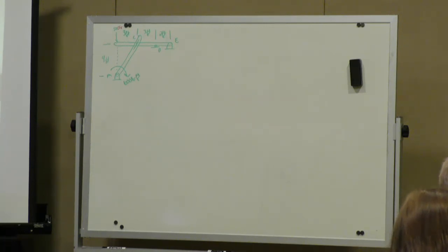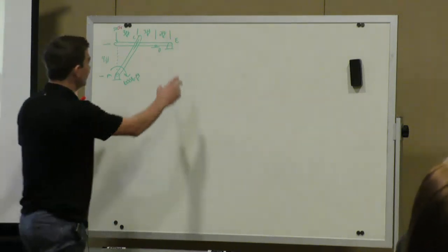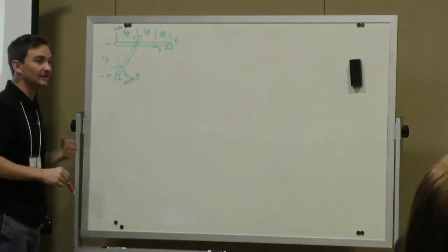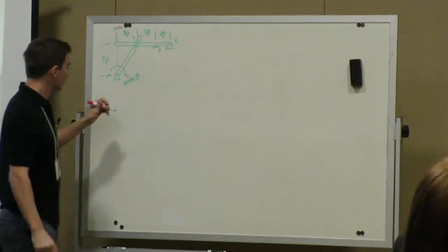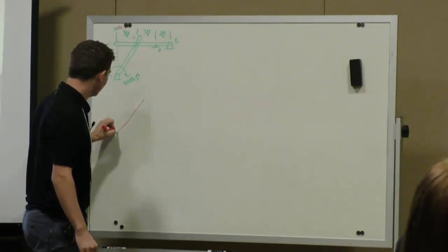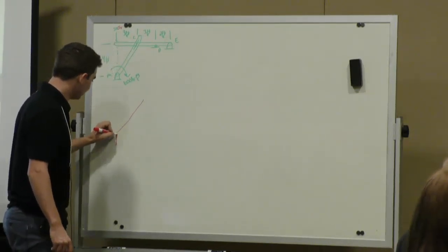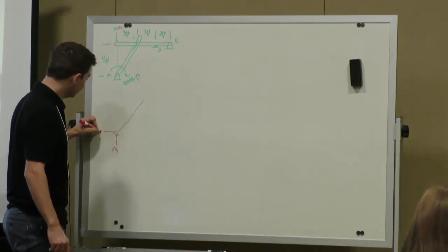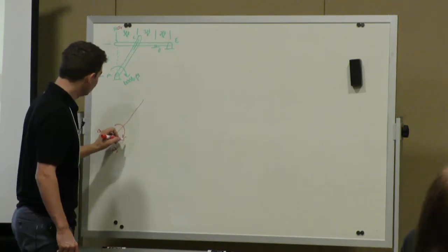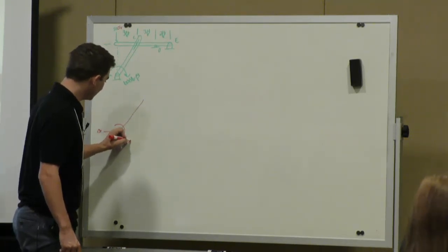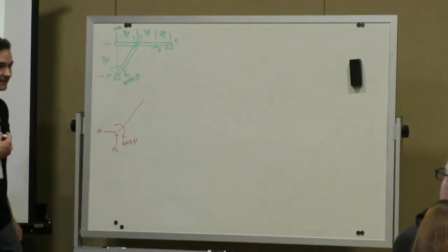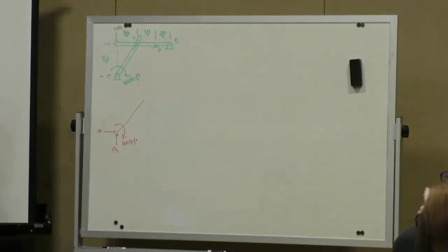So since we're saying this whole thing is in equilibrium, we could say each one of these members is in equilibrium, right? So if we draw the free body diagram of the first one, we have AY, AX, we have a couple moment of 600 pound feet. And what is our reaction going to be at C?